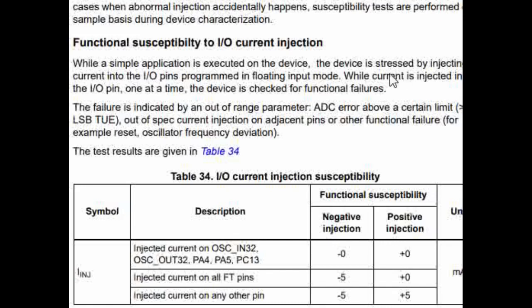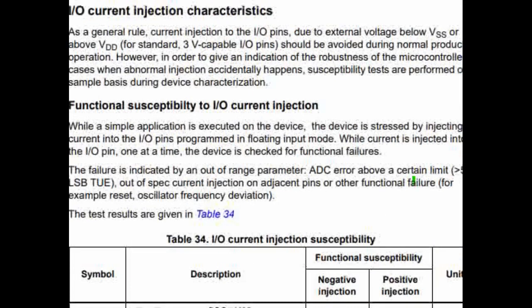While designing your circuit, it is very, very important that we don't exceed this current, otherwise the IC gets damaged. So injection current is harmful, but unless the current exceeds the maximum value, it might not damage the device, though it might still function inappropriately. In the worst case, in a microcontroller, it could lead to an improper reset condition occurring. And unless you power up both the devices connected on these specific circuits, the circuit might not function properly. A very important phenomenon.